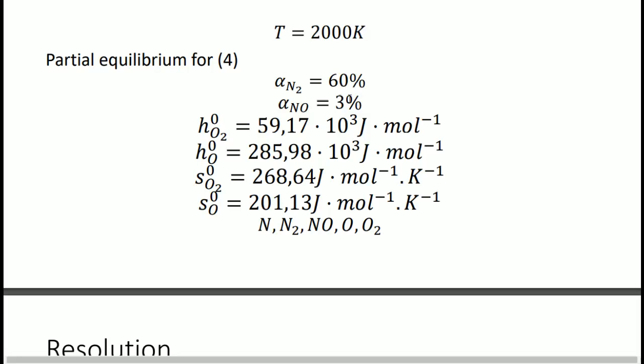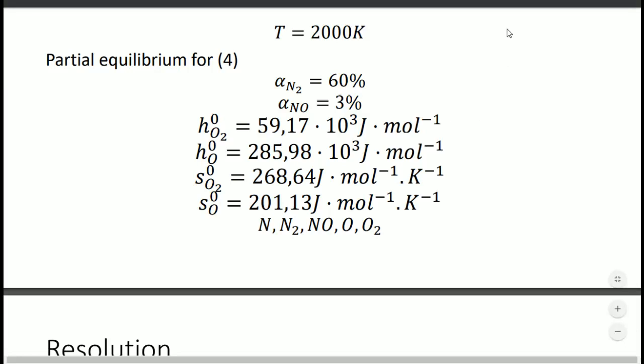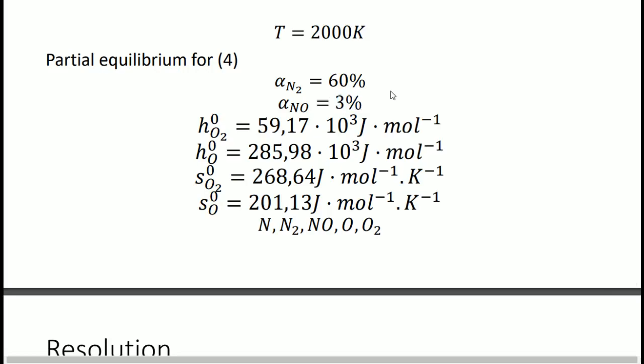So we will suppose that the 3% stay the same, because if the 3% gets higher, the combustion is weakened, so it acts less because of the reactions, and so it will have an equilibrium because there is production of NO, and when there is production of NO, it weakens the reaction, so it weakens the production of NO, and you get a pretty stable result. So we'll assume that the 3% are constant, and that everything that is supplement is added into the air.